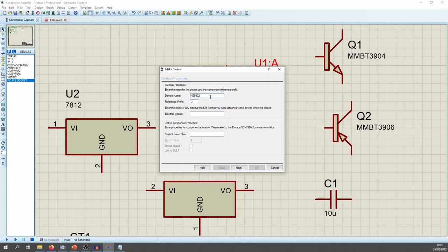The device name in this screen is the library name, so you can be quite descriptive. It's not going to appear in a BOM or anything. So I'm going to call this op amp. I'm going to call it a dual because there's 2 op amps in one package. I'm going to call it 10 megahertz because I remember what it was from the data sheet. And I'm going to go plus minus 22 volts. That's a lot of information about that part, and it's all searchable. I'm obviously keeping the name of the part as well, NE5532. It's actually the AP version, so I'm going to put the AP at the end of it. All that is searchable, so good stuff.